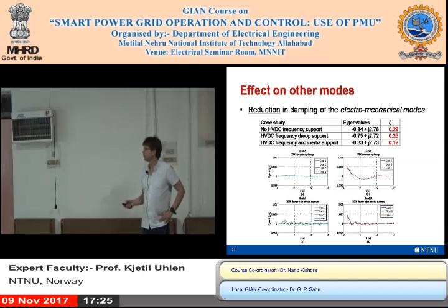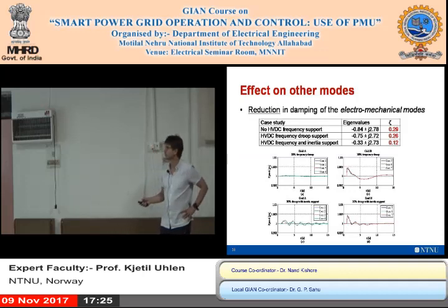And actually in this case, the solution with the inertia support resulted in a much reduced damping of the electromechanical modes. So even though it worked perfectly on balancing, it destabilized the electromechanical modes.